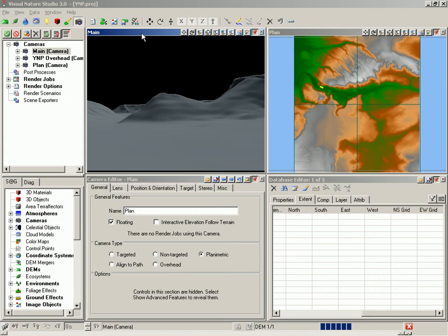Tiling is done during import for most data types, but the gap filling required by the SDTS DEM format precludes it. SDTS DEMs require a second import to tile the single DEM created by the first import. So if you still have that render running, stop it.